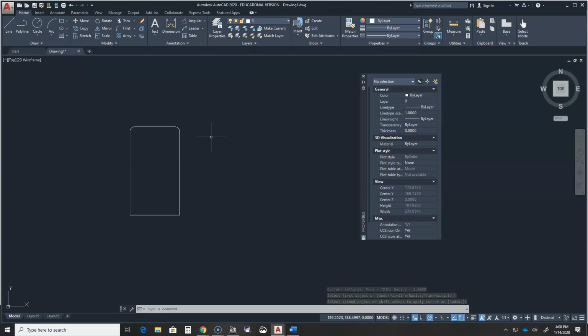Okay, now I can also change the dimension of that radius. Let's say I want to put a radius down here on this corner. I have to hit the enter button to get it to go back into the radius mode, and then click on this line. Well, I can type in R here also.